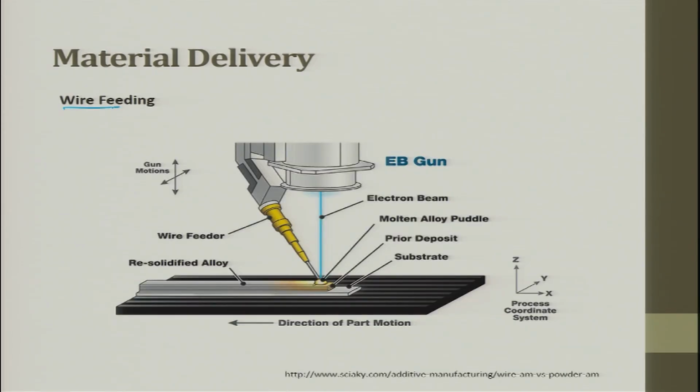So, wire feed. This is the wire which is getting fed. It looks like your MIG system and TIG system. So, this is a wire feeding coming up. Here is a laser. So, this laser or the electron beam comes and hits at the pool, and here it melts. Here is a melt pool we talk about. This is the molten, they call it a puddle, we will call it a melt pool. So, this is the wire coming here, electron beam can be replaced by laser.